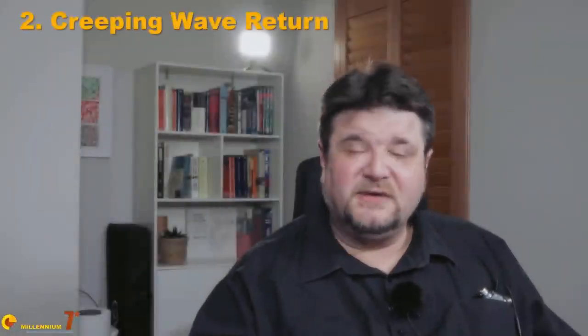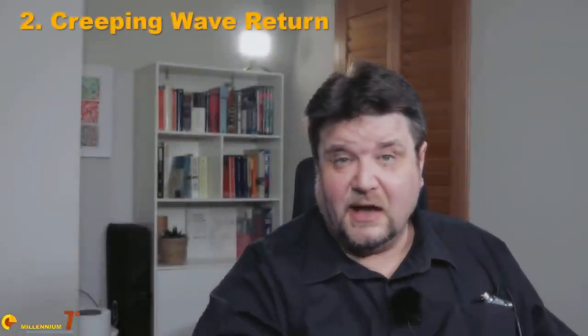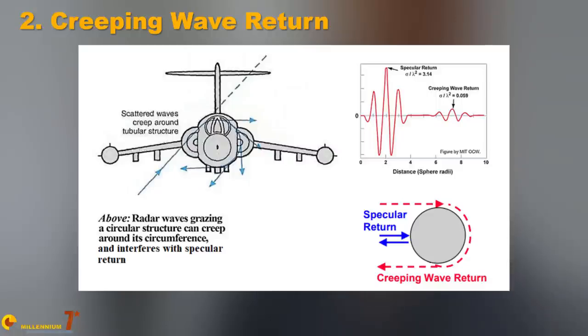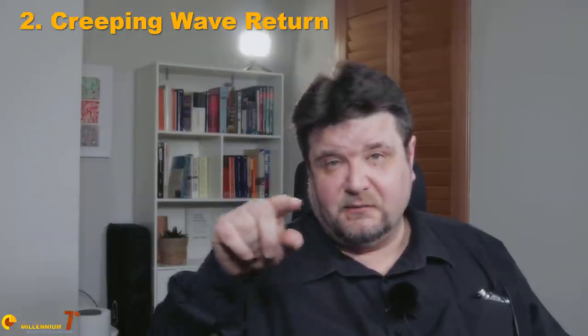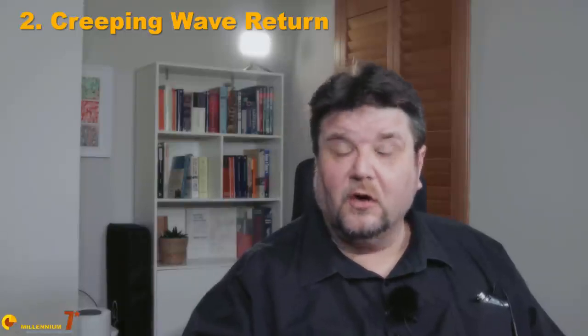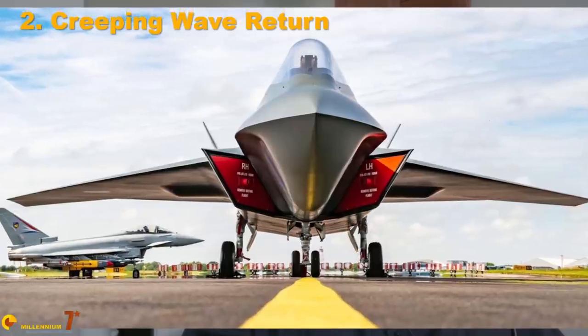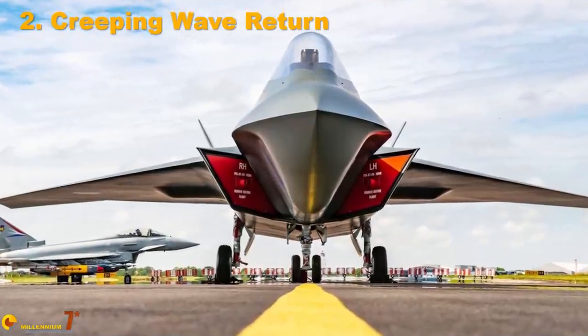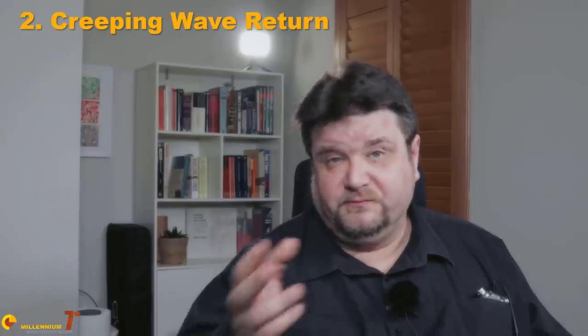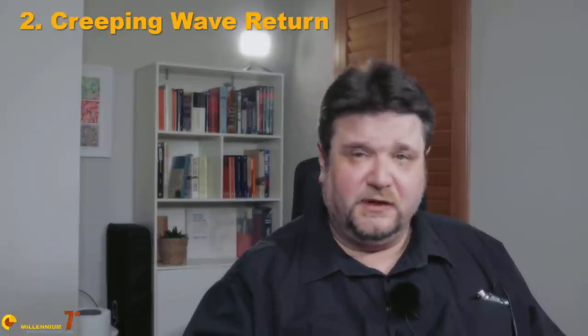The creeping wave happens when the surface wave that we have already seen actually travels along a circular element of the aircraft. For example, one of the panels or the elements composing an external drop tank. While the wave travels around its circular path, it emits radiation in every direction, including the direction where it came from. Another function of the edge that is so characteristic of the front section of stealth aircraft is also to stop the creeping wave from circulating all around the fuselage of the aircraft.